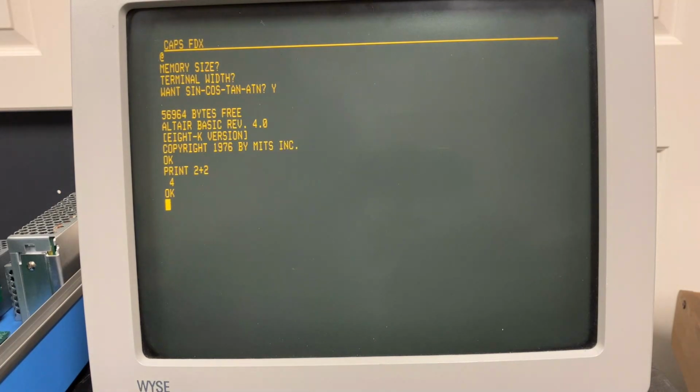All right, so that board works quite nicely. I'm not going to do any more demos. It's all stuff you've seen before. Now, there is one thing to point out about this board, and that is that the silk screen on the board for all of the address labels is basically wrong. On my board, it shows 0 as being up towards the top of the board and 1 as being down. In reality, it's the exact opposite of that.